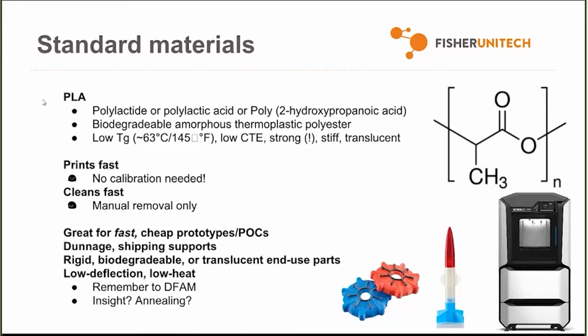Before every print, no matter what material you use, the tip will go back, touch the tray, home itself, and that's all that's required. That's part of every single print. So without that second material, there's no toggling of heads to go back and forth between the support tip and model tip every 2 layers. There's also no purge block required, which is normally required for ABS and other materials on the F-Series. That all translates to it building much, much faster than ABS, up to twice as fast for big prints.